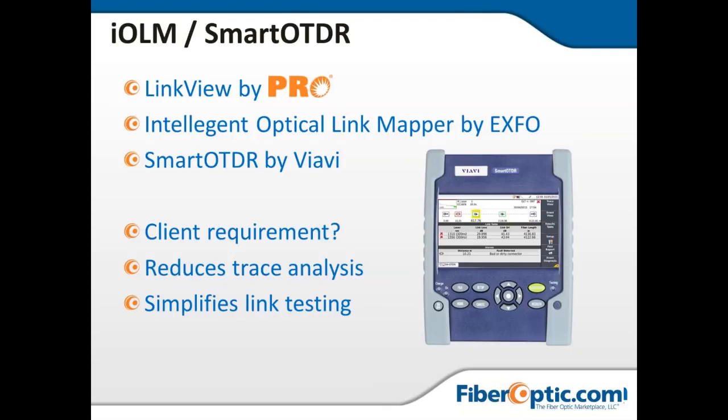Viewed in the trace. I absolutely require that my guys have access to the OTDR trace, because all of these systems make errors. It's not 100%. It's not foolproof. Don't go buy the Link View system. Great reference, get a quick straight line map of what you think is going on. But very, very frequently you get APC connectors misrepresented as bends or splice events because the reflections are so low because of that angled polish. So it'll put a splice somewhere that really is a connector. That can confuse people because it's guessing at what it thinks it is.